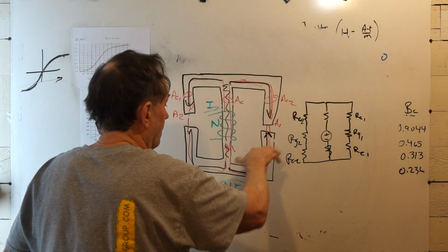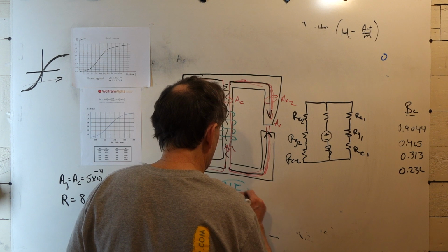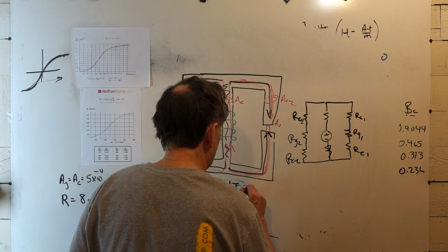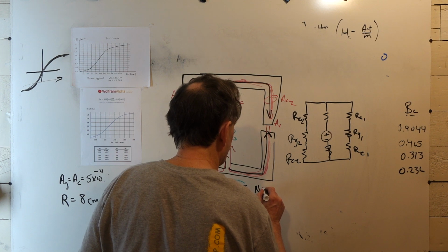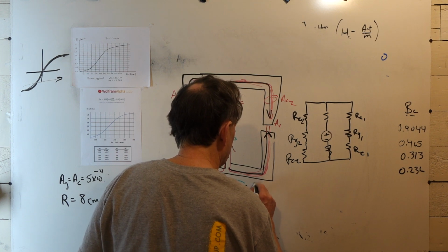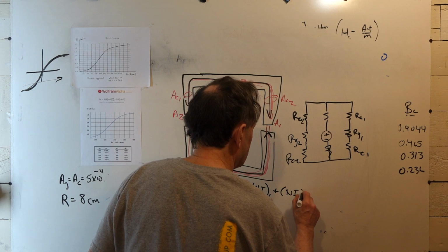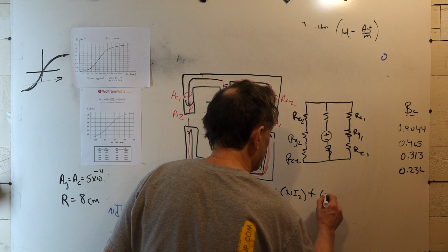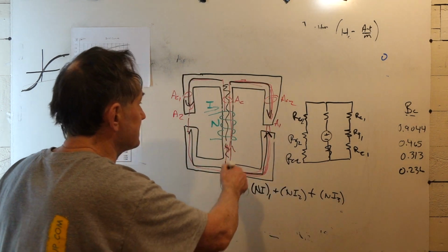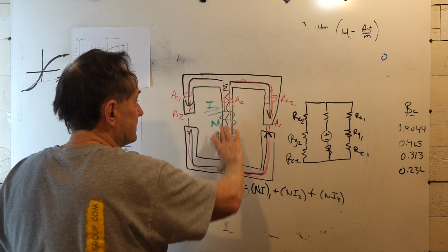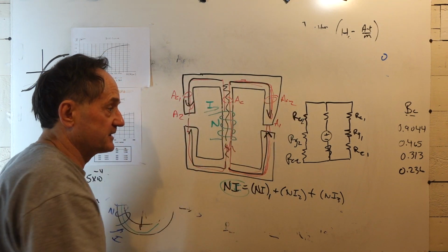And what's important here is the Ampere law equation, that Ni equals the ampere turns in various parts of the leg must all sum up to the driving magnetomotive force. And you'll end up with several equations, because you'll have an equation for the center leg and then another equation on the right and the left side.